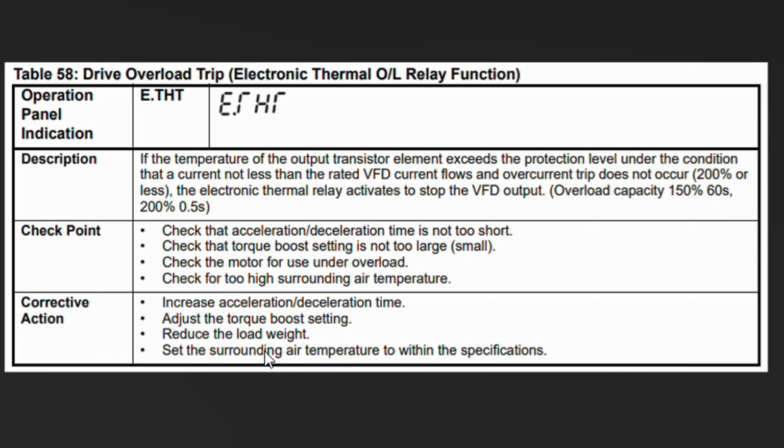It could be one conveyor belt and other things. Maybe the belt connected to the motor is too tight. And we need to check the ambient temperature, which should be normal and not too high. So these few reasons could cause this alarm. If you still haven't resolved the issue by checking these things, please write a mail to us and we will help you. And if you require a new VFD, you can also come to us.